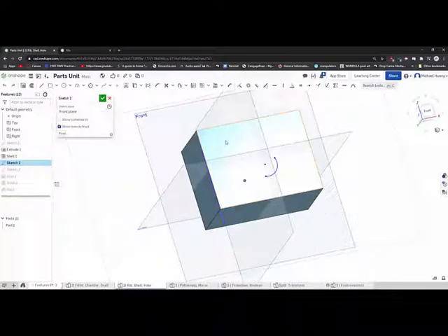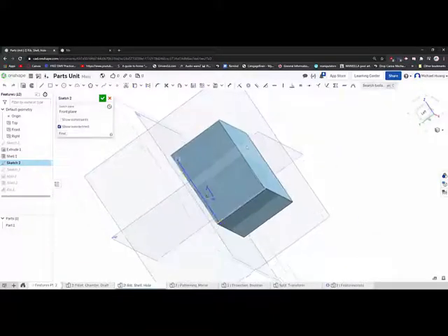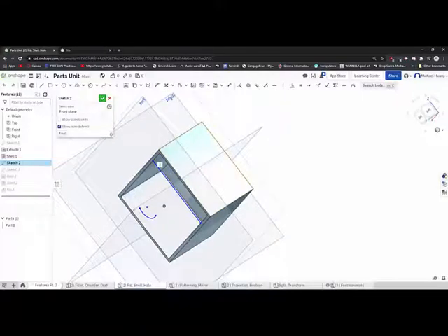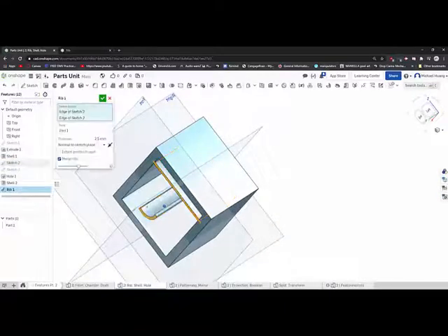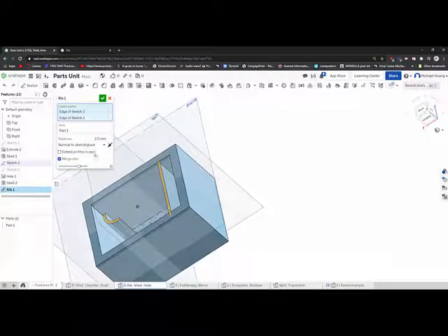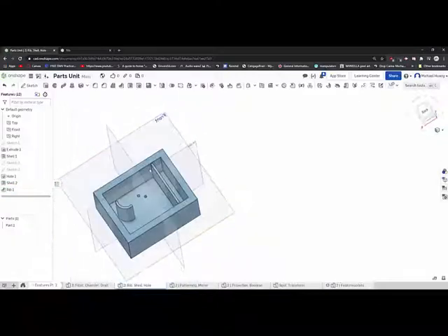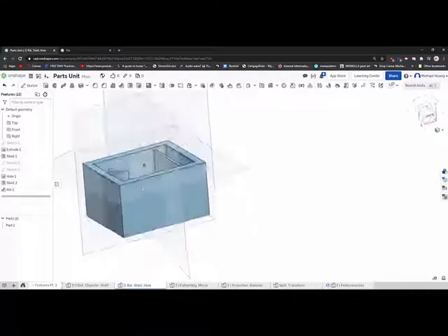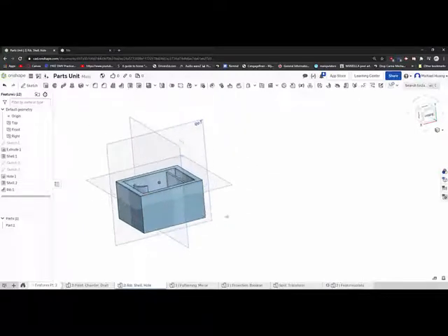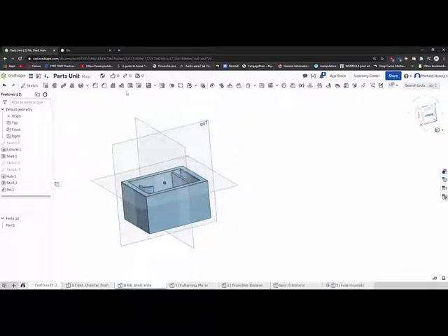And if I have sketches here, I can't really add material because there's a wall blocking my rib. All right, so keep that in mind. Here you can change the thickness of your rib. Pretty self-explanatory. Okay. And that about covers this entire set of features.